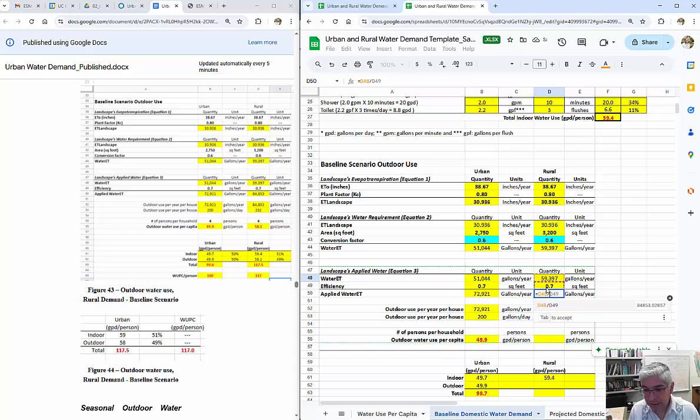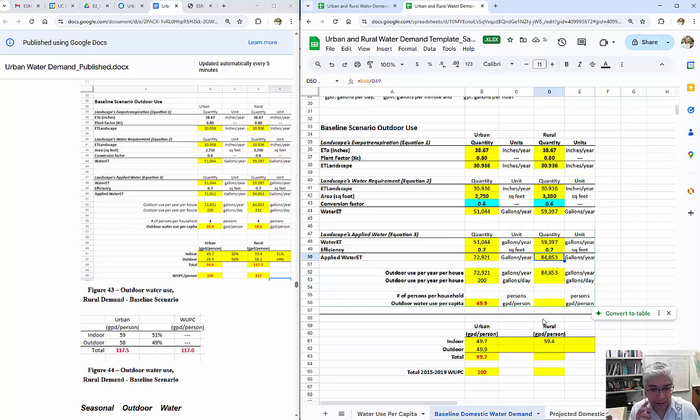So because it is that efficient, we need to use this much gallons to actually irrigate it. We are over irrigating in this case. And you can see that this is happening, for instance, when here we are in the campus, we're seeing that the pavement is well watered. You can see that irrigation systems are not that efficient, so that's why we're considering this value. Here is the same. We'll have to divide this over 365, and then this value over 4 people.